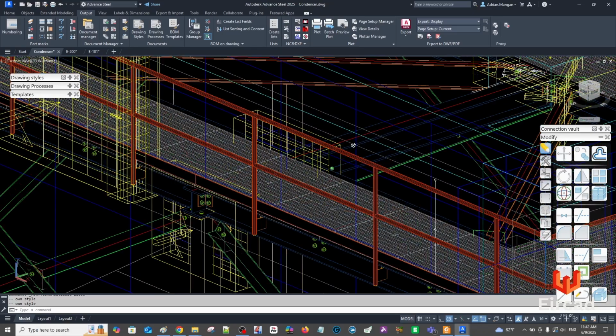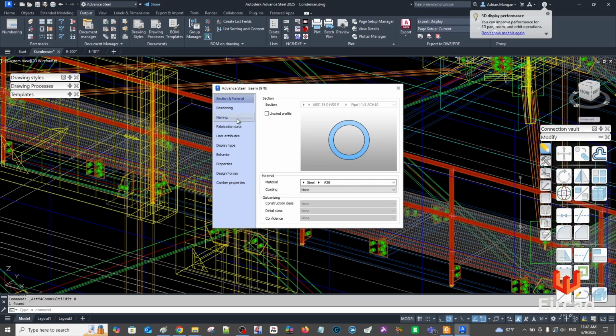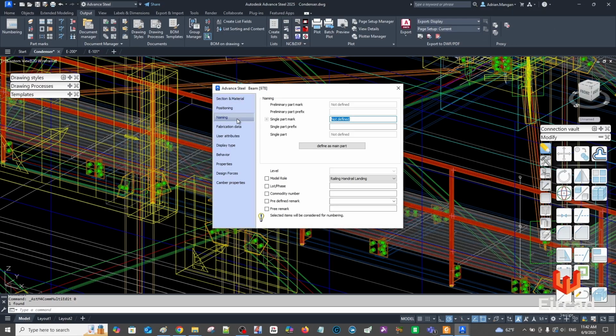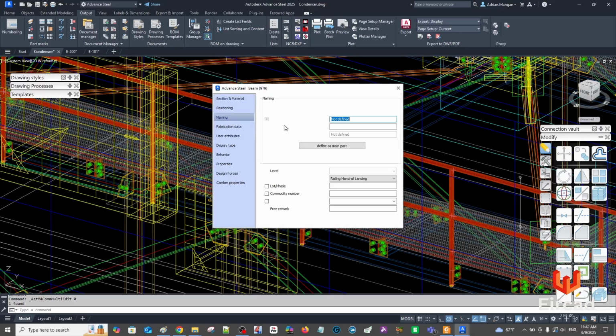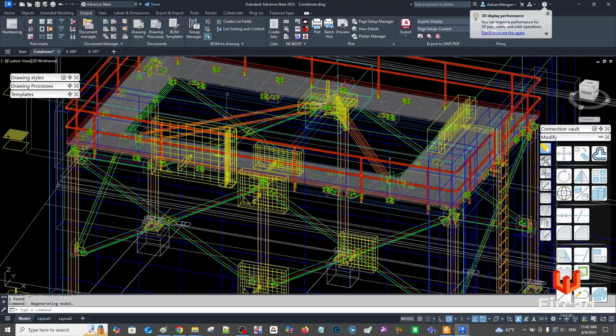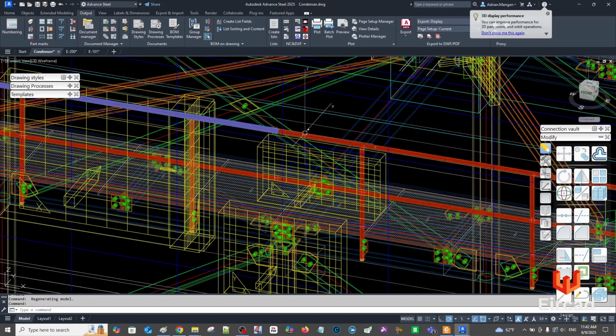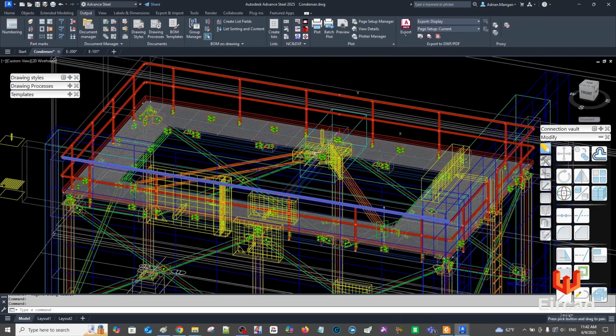Now, did I do something with this handrail? So if we check this one, railing, handrail, landing. So they're the same model role. Now, just so you know, these aren't finished handrails. The macro just splits them wherever this beam is. So right now I'm just waiting for approval. Then I will end up redoing these handrails and putting splices in different places, like over here, probably. So just in case you're wondering about that.